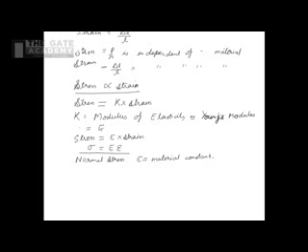Now, what is the unit of E? If we see what is the unit of stress, sigma is force upon area. The unit of force is Newton and area unit is meter square. So the unit of stress is the same as the unit of pressure, which is nothing but pascals. Now there is another practice which is to define the area in millimeter square, in which case it becomes megapascals, but that is not required right now.